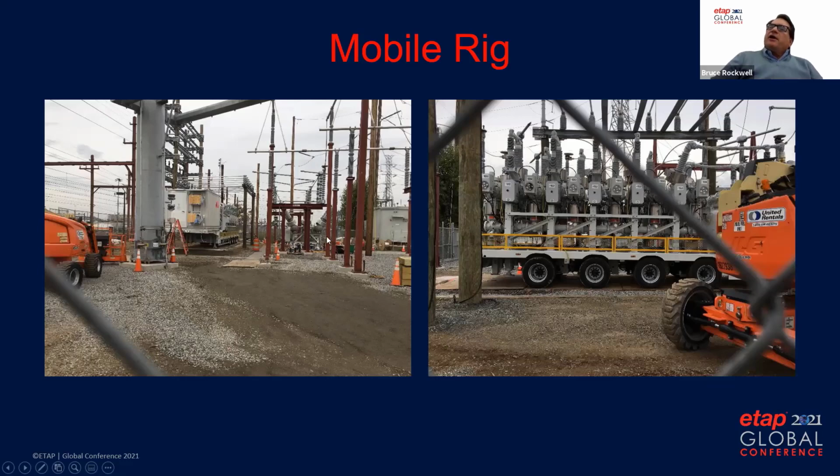So this particular client decided to purchase a mobile auto transformer and mobile traction power breakers all on one trailer. This mobile substation was installed, which required us to do further evaluation on the load flow of the revised impedances of the system, as well as looking at the contingencies in case there was a failure while we're feeding in this compromised design state due to construction and upgrades. And this protection and control system had to be evaluated.